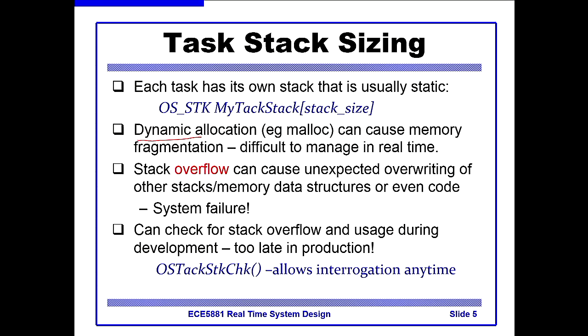Some bits are used and there's free space and other bits are used. So that creates a difficulty. If you want a big slab of continuous memory, you may not be able to do that without reshuffling all the allocations, which is time consuming. So you'll find in a real-time operating system you have these special allocation mechanisms that don't have those problems.